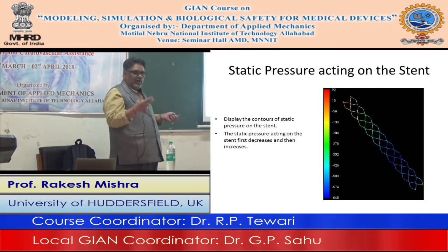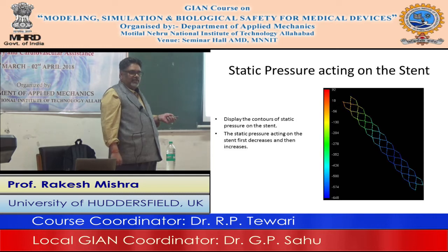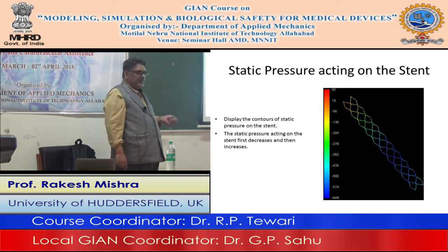And this pressure, if you have an FEA model, you can put into the FEA model and calculate the deformation of the stent elements because of the static pressure as time goes on. So that is the FEA part you can do if you are doing flow structure simulation. Okay, any question on this, please?